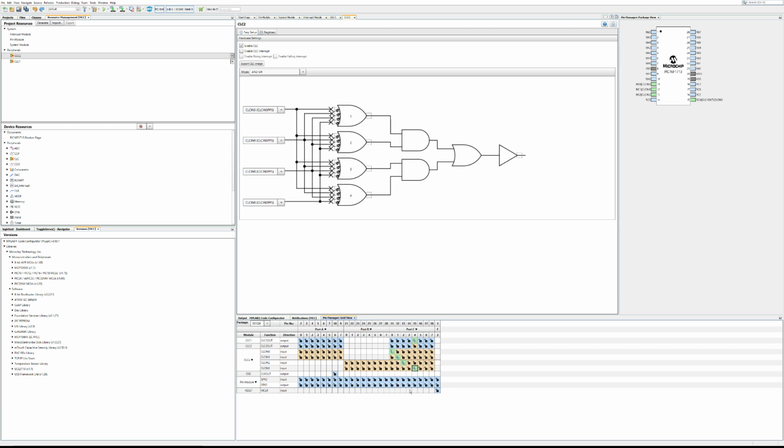The disadvantage of this is that it does occupy an I/O pin. The advantage of this is that you do actually get a point to probe into the internals. You can see what the signal is when it's passing between the CLC modules by probing that pin. So it's both good and bad, but in a device like this where we're basically just using it for digital logic, it's not really a big limitation. So yeah, rather cool.